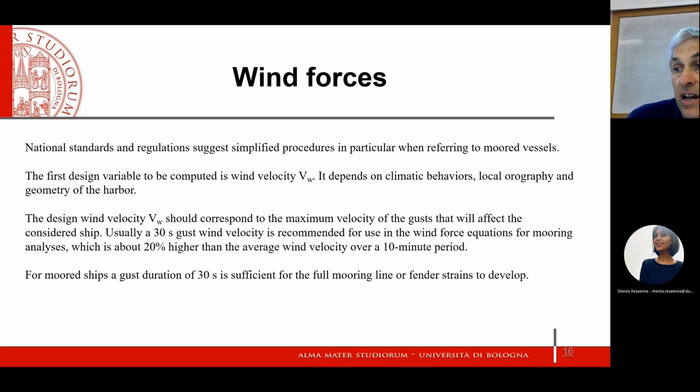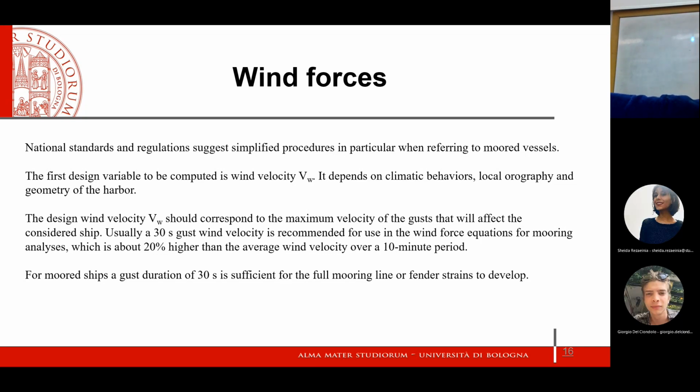So we have this gust coefficient to introduce. And I mentioned the gust duration of 30 seconds. Usually, this is the gust time that we adopt. We are recommended to use. You have to see the regulations, of course, but very often you will see that the order of magnitude is 30 seconds.